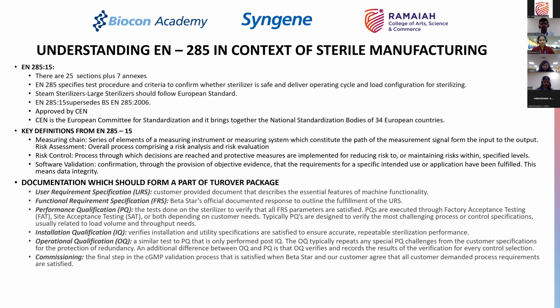Functional requirement specification. Now, this is a document which is a part of what is called the design qualification, which is submitted by the vendor after you give the URS to him and you place an order on the vendor. He is supposed to give you a functional requirement specification along with the design qualification. What does that mean? You have given him a user requirement specification. He has given you an offer. You have shaken hands and you've given him the order. Now he is supposed to give you how he is going to design the equipment so that it meets your user requirements.